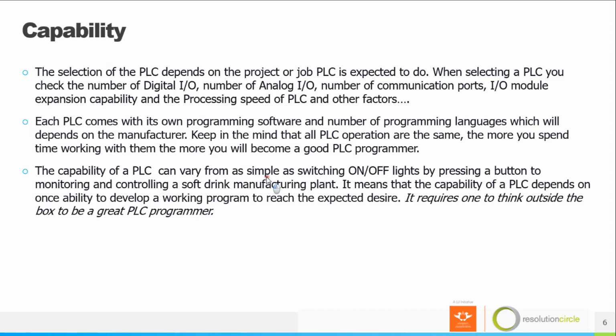You should also check the processing speed of that PLC, how fast the cycle can repeat itself, like how long the PLC takes to read the input, execute a program, and update the output. All those things. You select a PLC based on your application or your specific job.